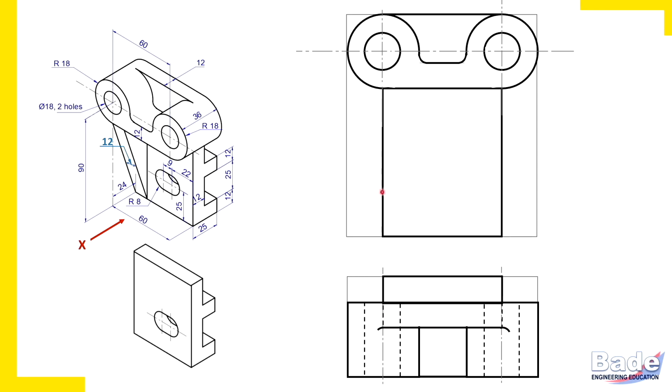So where is this part in the top view? So again, show me this complete rectangle. Each and every part in each and every view you must be able to identify. Then only will you be able to read orthographic views properly, or construct orthographic views properly. This is that lower portion.